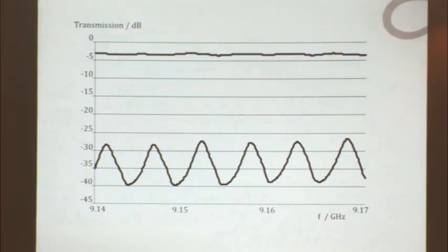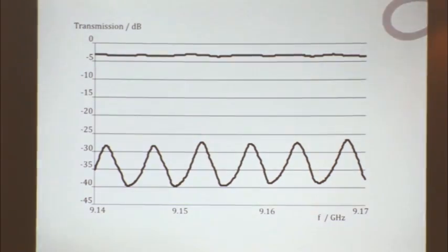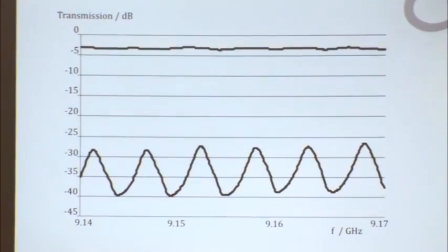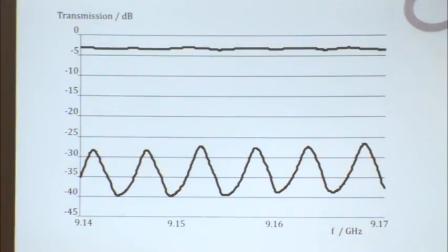And here are the results. This is what I measured with a Rohde and Schwarz network analyzer. I mentioned that because it's a very expensive and very good tool to see how the signal behaves over frequency. And what's interesting, without the tunneling pieces, I have a flat transmission, and the signal is damped by approximately 3.5 dB. That is the natural damping because of the 20-meter waveguide.